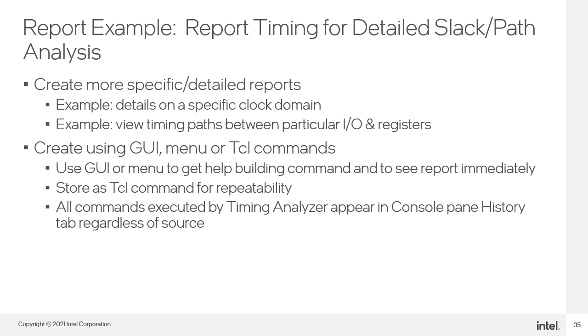When you generate this report, the default will be to send the report into the GUI so you can do a graphical analysis of that path or paths, or you can send the report to a text file. You can capture the details of how you generate the report in a Tcl file so that you can automate the creation of this report every time you need to compile the design.